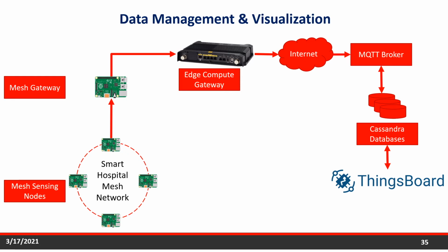We chose this deployment scenario to address the challenge of limited range communications in geographically spread deployments. Next, data is transferred using secure copy protocol and hops between multiple nodes until it reaches the mesh gateway. The mesh gateway aggregates data from different nodes and does the necessary protocol translation. From this point forward, data communicates using publish-subscribe protocol, which is MQTT.